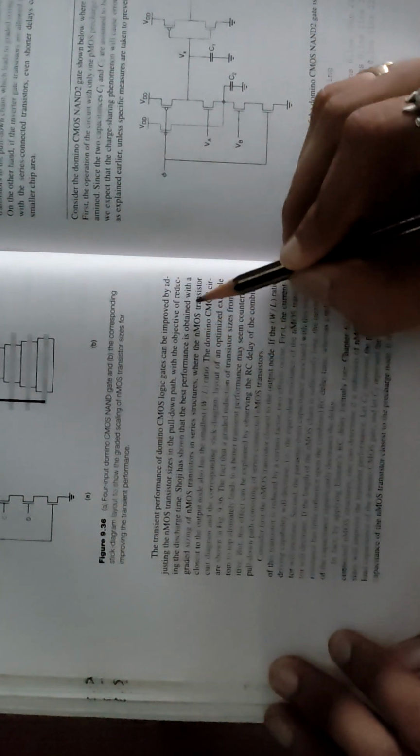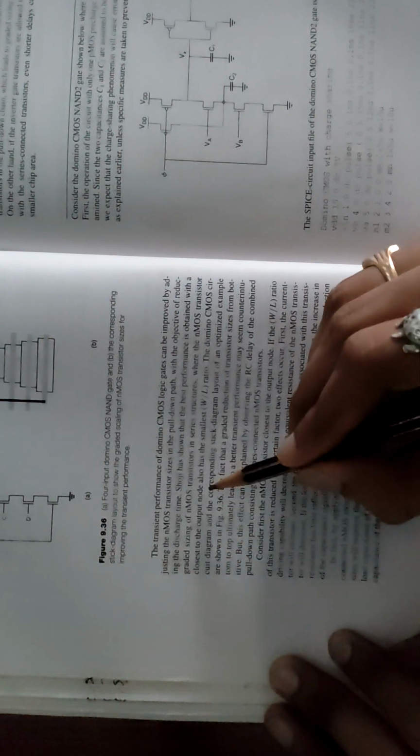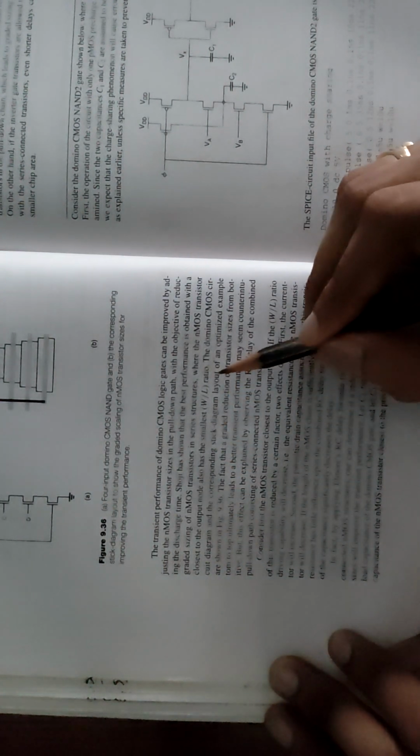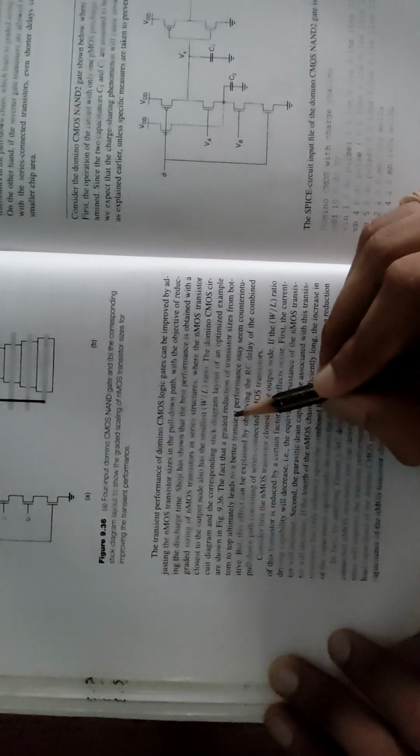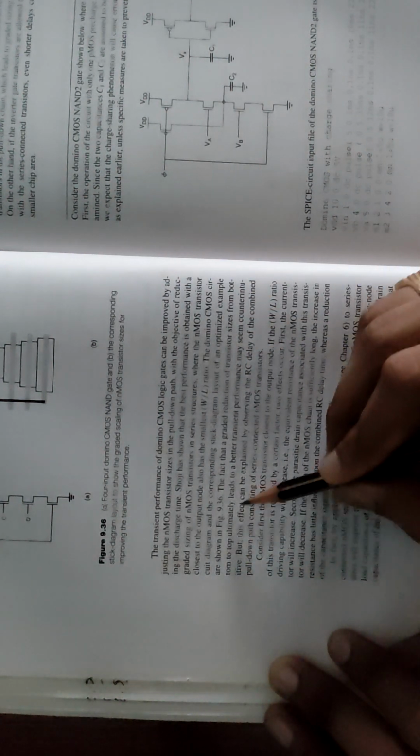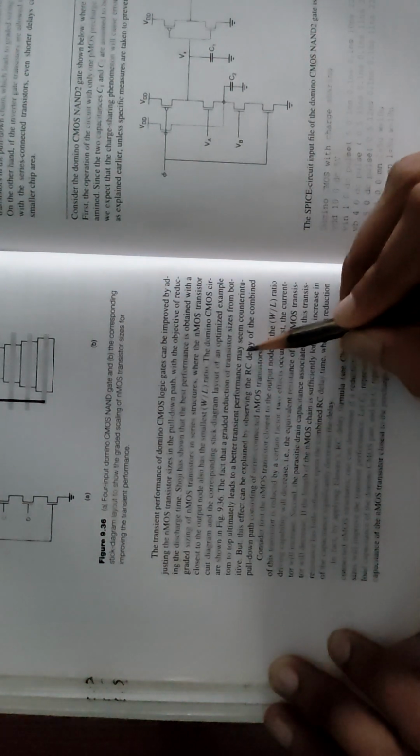Soji has shown that the best performance is obtained with a graded sizing of NMOS transistors in series structures, where the NMOS transistor closest to the output node also has the smallest W/L ratio. The domino CMOS circuit diagram and the corresponding stick diagram layout of an optimized example are shown in the figure. The fact that a graded reduction of transistor sizes from bottom to top ultimately leads to a better transient performance may seem counterintuitive,